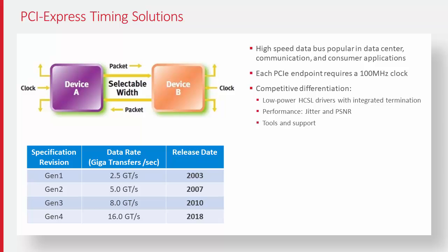Yeah, I have a few questions for you. First off, what is PCI Express? Yeah, very good question. PCI Express is the abbreviation for Peripheral Component Interconnect Express, or commonly known as PCIe for short. It is a high-speed serial point-to-point interconnect standard developed and maintained by the PCI Special Interest Group, also known as PCI SIG. The serial interface sends both data and clock using the same wire, allowing for high scalability in transmission rates, reduced complexity and cost compared to the older parallel transmission architecture.